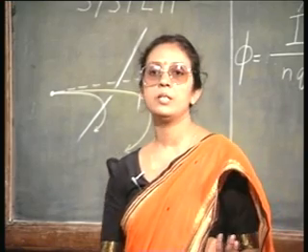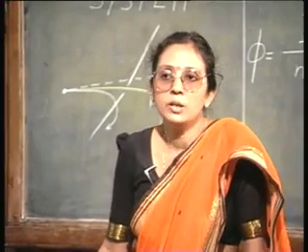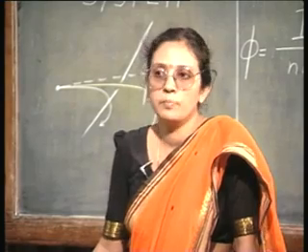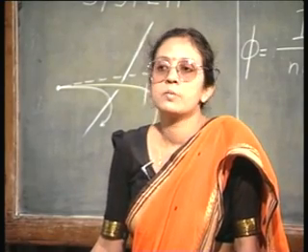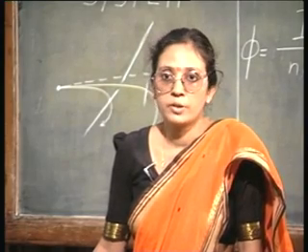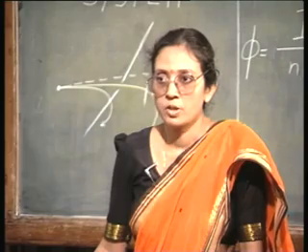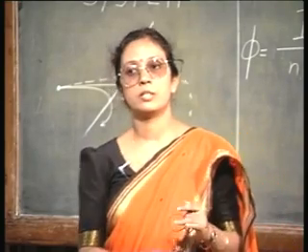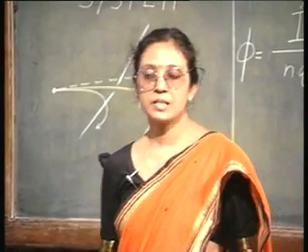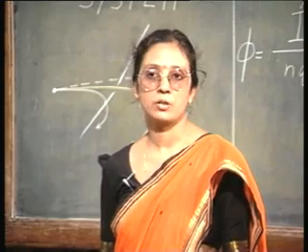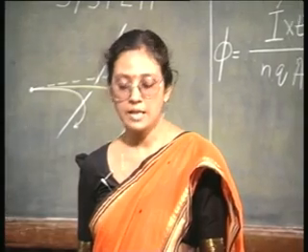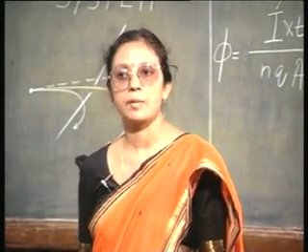Now, so far you see we have discussed only the positive aspects of implantation, that is we have discussed how good implantation is, how much better control, how much flexibility it offers compared to diffusion for example. But do not let us forget that implantation actually means physically you are hitting the semiconductor surface with a stream of high energy particles and in the process it is going to create damage.